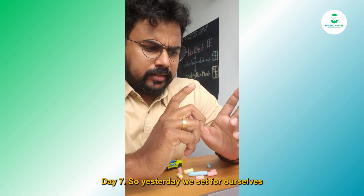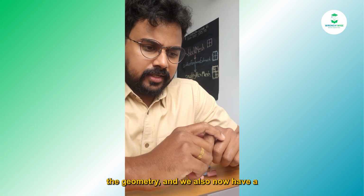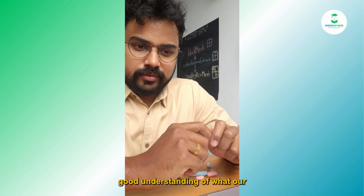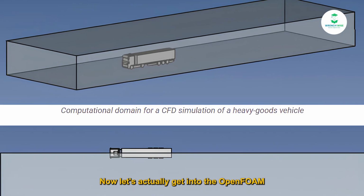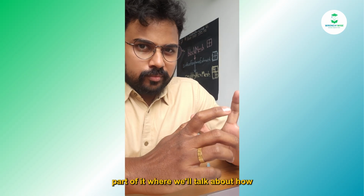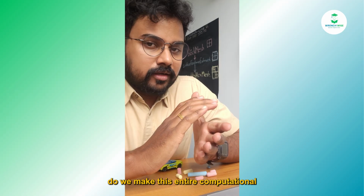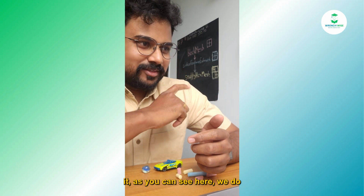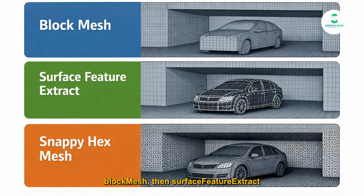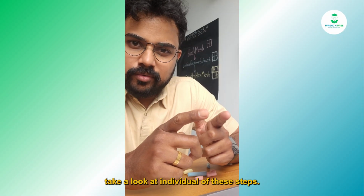Day 7. Yesterday we set the geometry, and we now have a good understanding of what our computational domain should look like. Now let's get into the OpenFOAM part, where we'll talk about how we make this entire computational domain happen. The way we do it, as you can see here, is blockMesh, then surfaceFeatureExtract, and ultimately snappyHexMesh. Let's take a look at each of these steps.